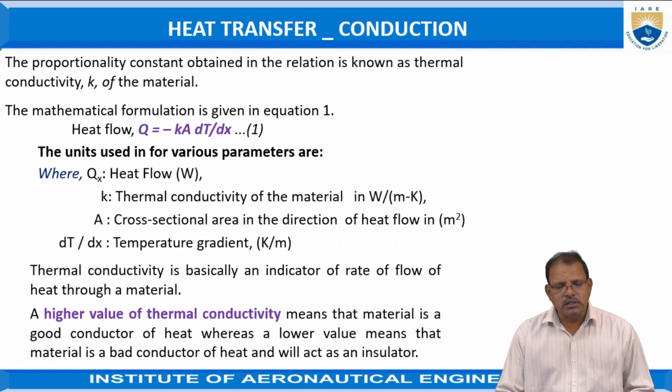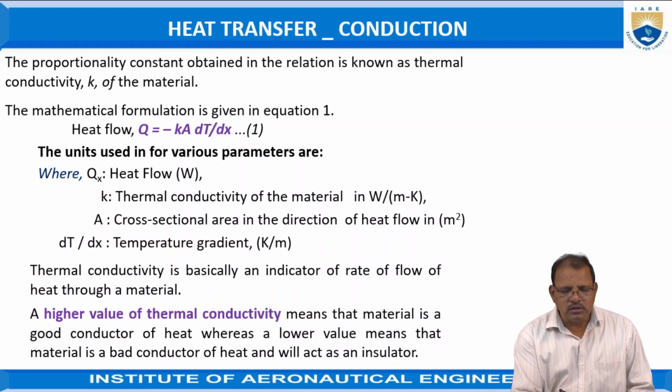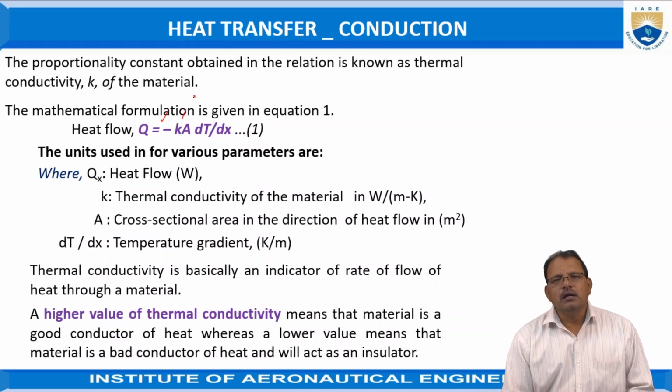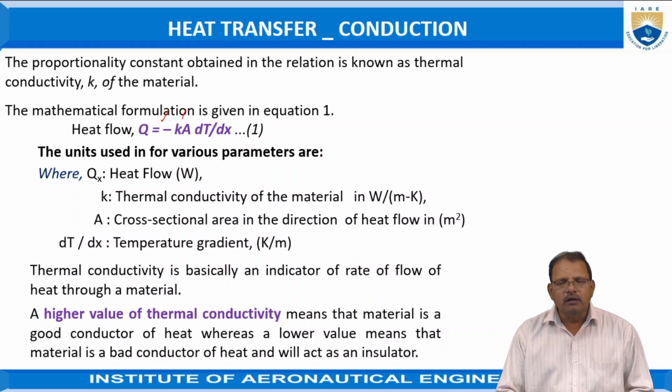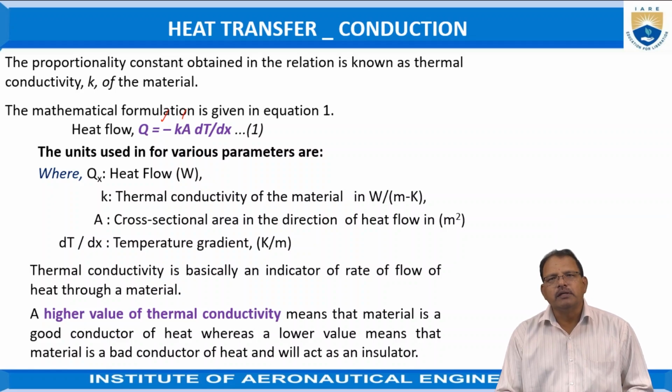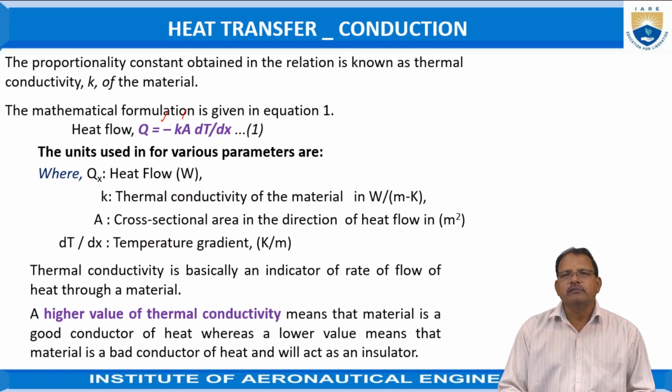So, according to Fourier's law, the amount of heat energy that flows between two bodies, or from one point to another in the same body, is given by the equation Q = -K A dT/dx. Here dT/dx is the change in temperature per unit length, generally treated as the temperature gradient, and it is always expressed as negative. K represents the thermal conductivity of the material, which depends upon the property of the material.